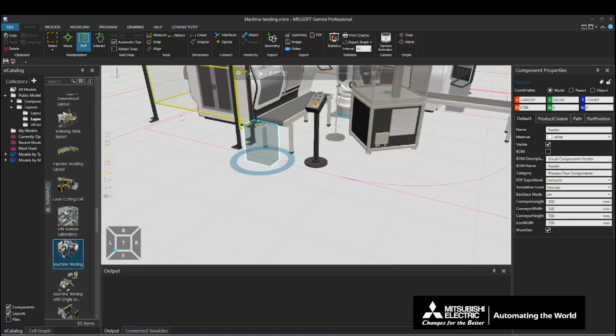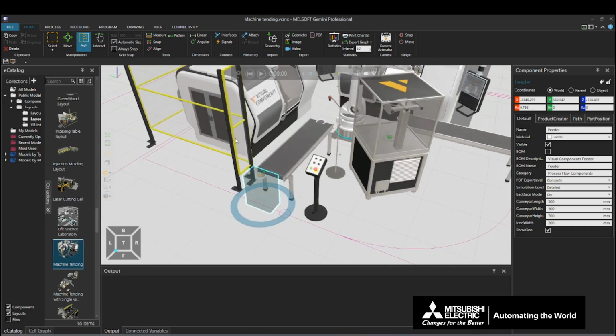The PNP command moves a selected component and connects it to another component close to the move destination. The direction and position of the components where a connection can be made can be determined by whether there is a yellow triangle mark on the component.